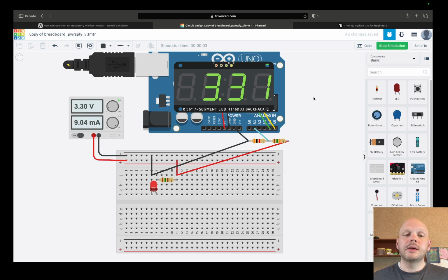And it's the same thing. If you look here, this is the negative rail, this is the positive rail. Between this negative and this positive is 3.3 volts, right? Well, this wire right here is just coming down, and we're measuring from here. And this wire here is just coming down, and we're measuring from here. So there's no difference, because this is like saying we used a longer wire to connect back to this point. There's no difference whatsoever. I just wanted you to see that we can measure at different parts of the circuit, and depending on how we've connected things, it can be exactly the same as what we're feeding into the circuit.